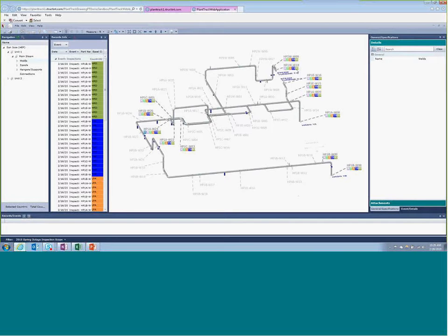Moving to the next thing. So we've got this scope of work built. Now we're going to go through and actually do the inspection. So how does that work, and how does that data get displayed in here? We have these welds that we're going to look at. So we've come through, we've done the inspection, we've done the mag particle, we've done all of these methods on these particular welds. So when that's all said and done, okay, well, findings. What are the things that I need to worry about and need to stay ahead of?